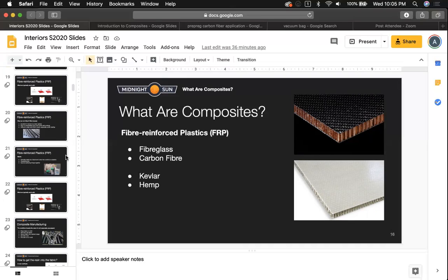It depends on the size, I guess. The one difficulty with the whole prepreg situation is the oven needing to bake the part, whereas infusion or wet layup can happen at room temperature. Depending on if we do some math to figure out the weight of the actual part, if it's a relatively small part, it may not make a lot of sense to use prepreg if it's just as easy to do with a wet layup.